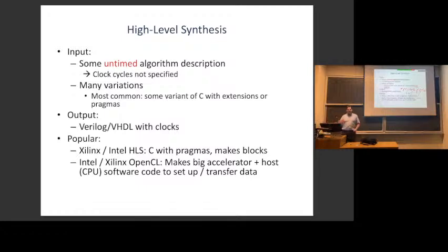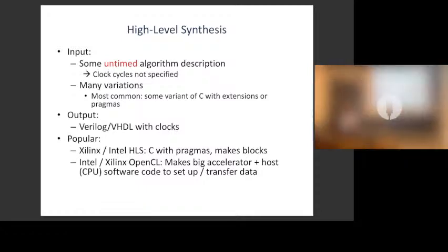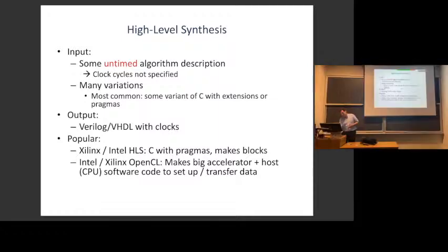Your end goal is you're putting all these pragmas in, using a special tool to turn it into HDL, like Verilog, and you're trying to get higher performance. That's why usually high-level synthesis tools now use pragmas rather than just making up constructs, like making up new keywords in the language. Because if they make up new keywords, you can't actually compile that code in a conventional compiler at all. Okay, the output, as I said, is HDL with the clocks put in.